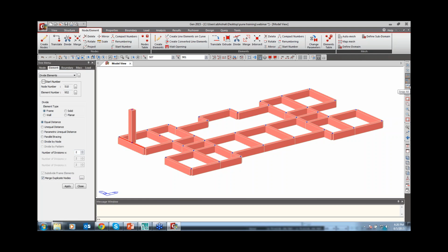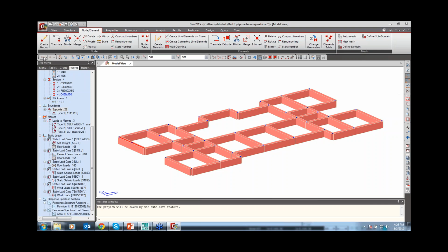So in this way also, if you want to generate from the floor, you have to create the plate element and then you can generate it. So it's up to you how you want to perform it. So in this way also you can perform. And now the next question is how to create these stub columns or floating columns from the floor to frame. It is okay.